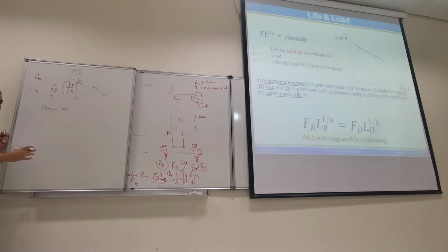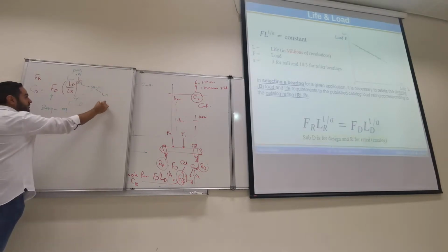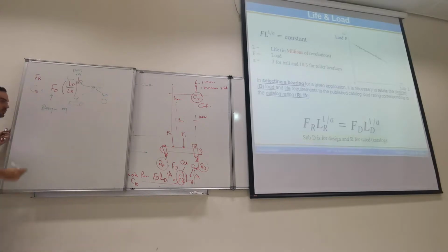And we said that the applications are different. For example, if I have a very high radial load, I prefer to go with a cylindrical roller bearing. Why does a cylindrical roller bearing carry a larger radial load? Because of the surface contact. The contact is a line in the cylindrical roller bearing. The roller is a cylinder like this, while in the ball it's simply a sphere, so the contact is a point.